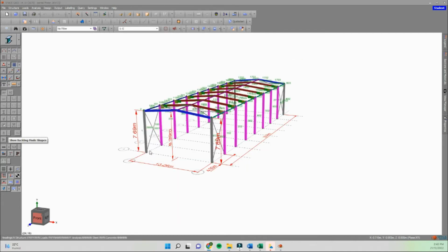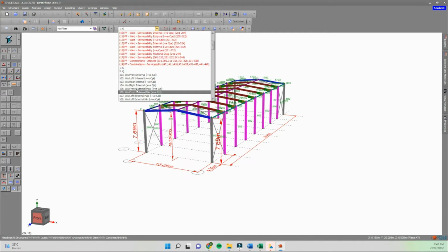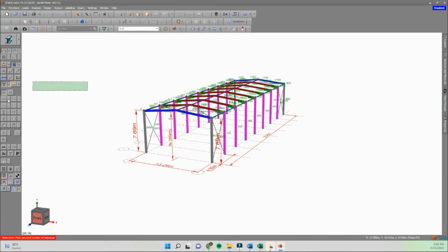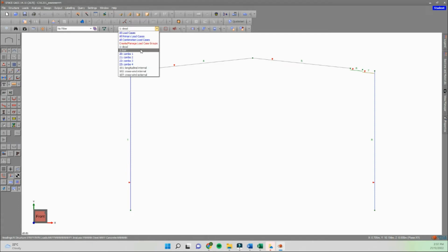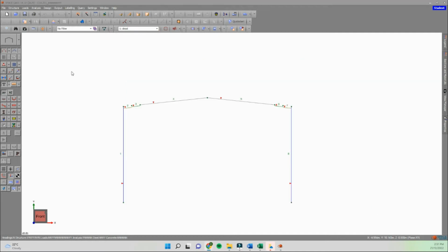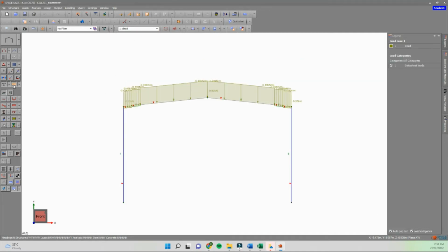The analysis of the portal frame through Space Gas was conducted to understand and determine the forces acting on the structure. Using a combination of both the 3D and 2D models, the team had the ability to find the actions of our 5 primary load cases and a number of combination loads to simulate limit states of our structure. The primary load cases utilised in this analysis were dead load, G, which refers to the load of all structural components in the building; live load, Q, which refers to the loads that are not permanent and change depending on